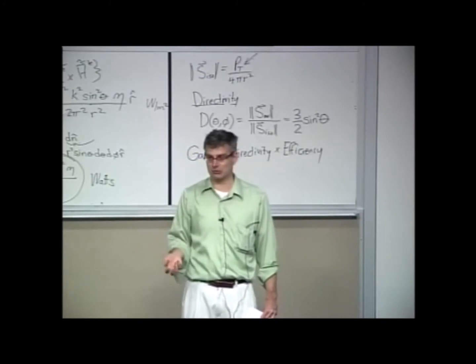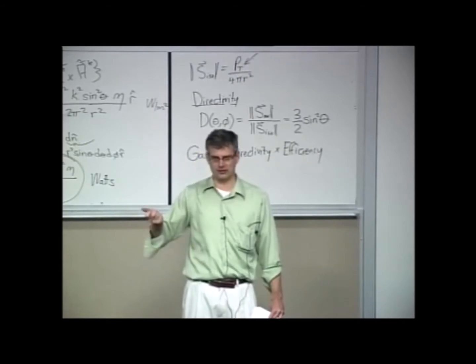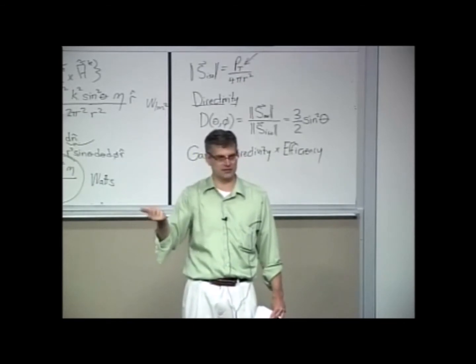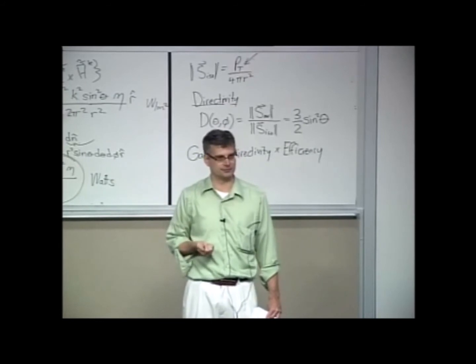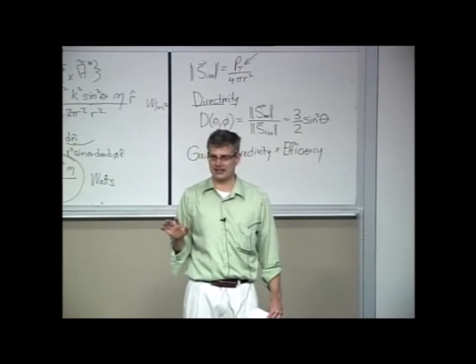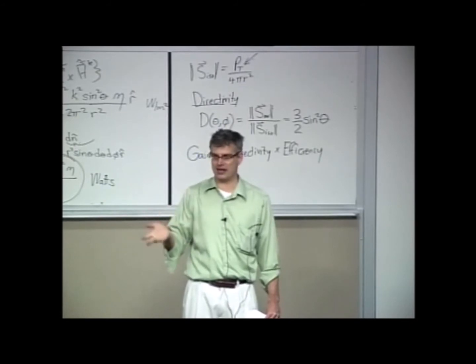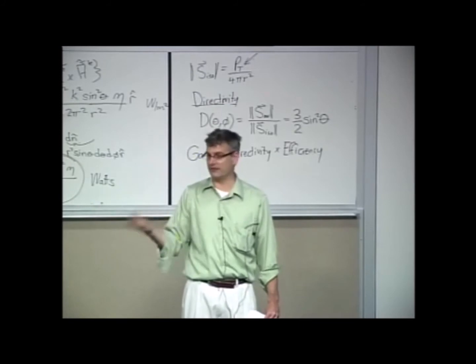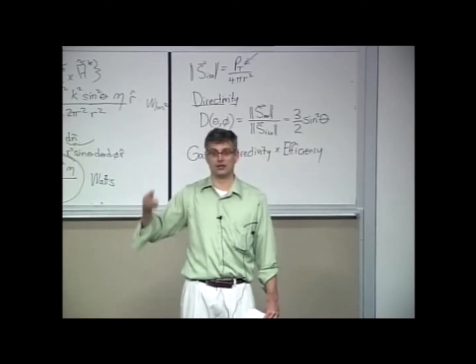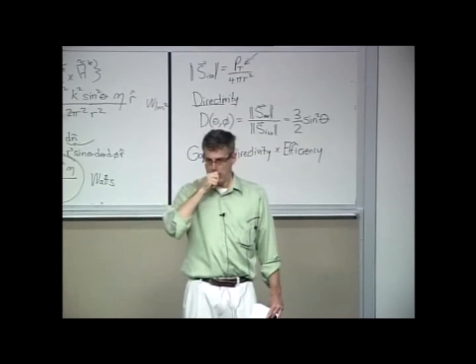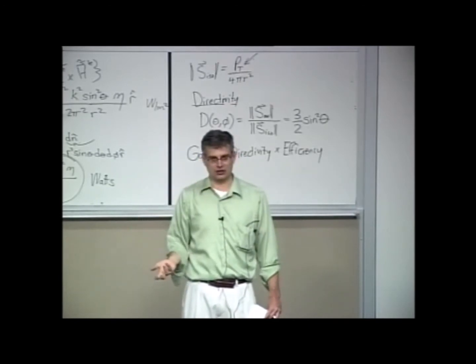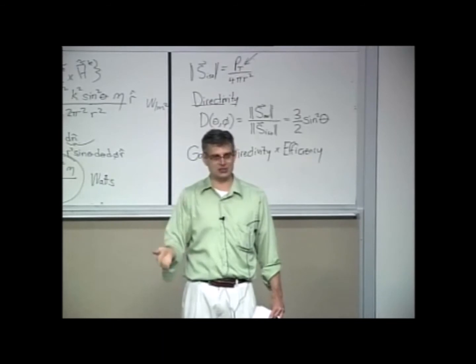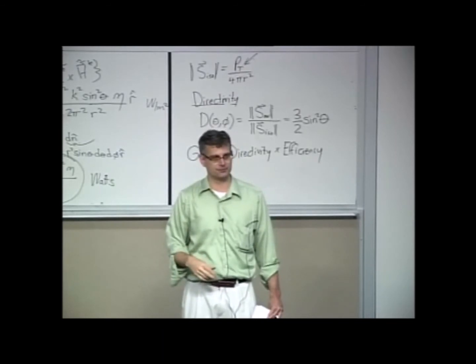If not, you get a matching problem on your hands, and you have to put a balun or a matching circuit of some sort in between them. Usually satellite engineers don't worry about that level of detail. The antenna engineer has probably figured all of that for you. The antenna that you spec out is usually given its parameters matched to one of the standard transmission line feeds, for example, 50 ohms. They've got some matching circuit in there already, and they basically tell you what the gain is with respect to 50 ohms.